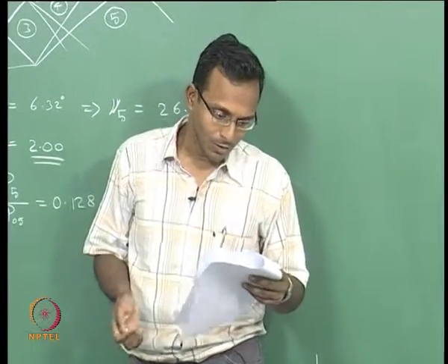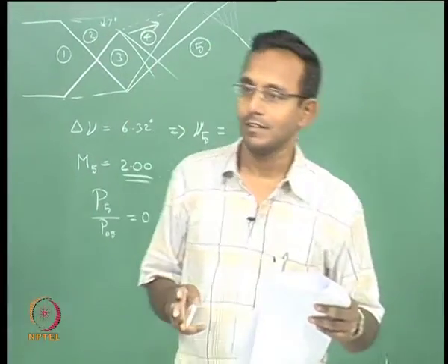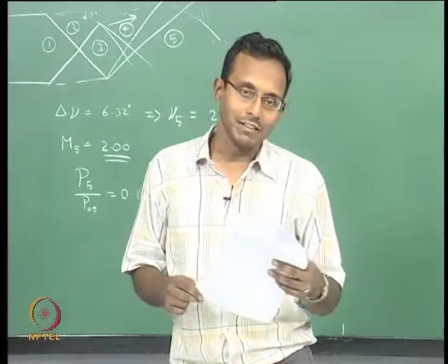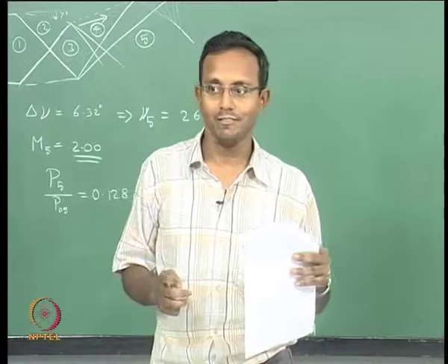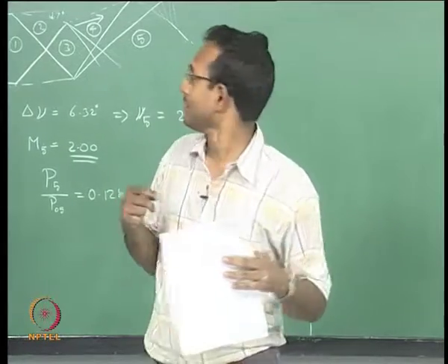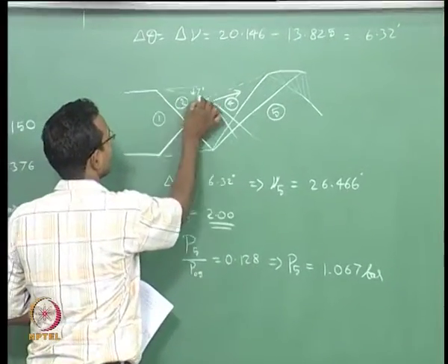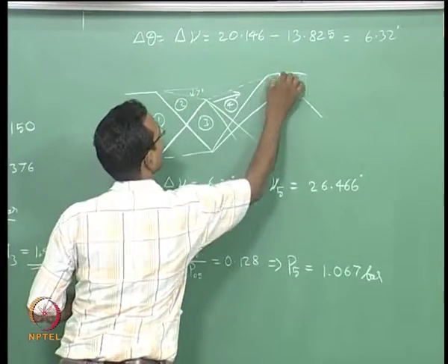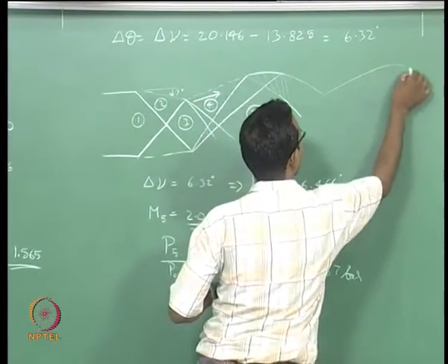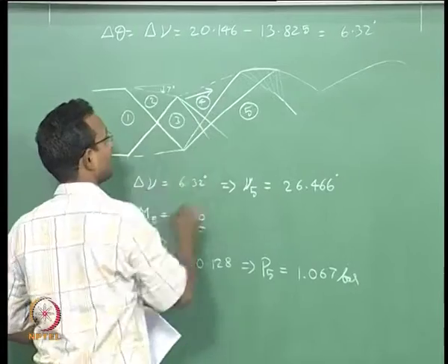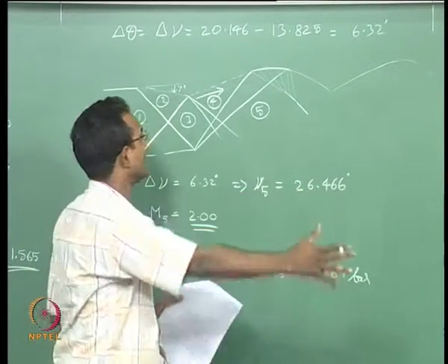Okay. Now I will stop the jet discussion right there. All this time we did not think about viscosity in my gas, and I said that if I have viscosity, my jet, I have a picture here, so I will just use this. My jet boundary is something like this, and then it is going out like this, and then it is turning like this, and I said that it will go back down, it will go back up, again have the same cell structure. This whole structure keeps repeating, and I said it will repeat forever. How many ever cells like this?